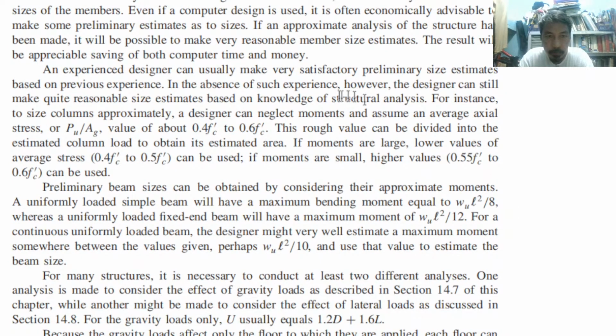So, an experienced designer can usually make a very satisfactory preliminary design estimate because of this previous experience. For instance, to size columns appropriately, a designer can neglect moments and assume an average axial stress, or ultimate force divided by gross area.